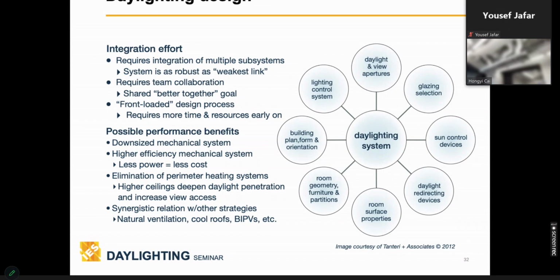For example, you will design a window, make it openable for natural ventilation, right? Or you design a window for daylight purposes, but you design another window just for natural ventilation purposes. So they are closely related. You don't want to separate them. You don't want to say, I'm going to design my building and then I will build my natural ventilation later. No, you will mess it up. Okay.